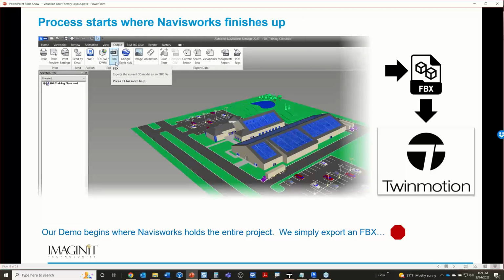So I'm going to start my demonstration process here, and the demo begins where Navisworks traditionally leaves off. In the traditional workflow for the factory design utilities, usually everything ends up in Navisworks for the final visualization. Well, I'm going to start here. I'm not going to open up Navisworks for this, but all I would do to start this process is go to the Output tab in Navisworks and export an FBX.